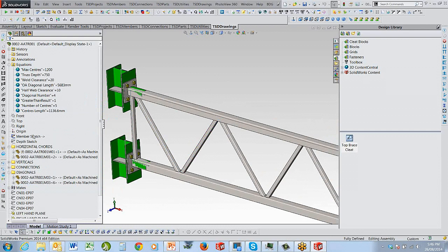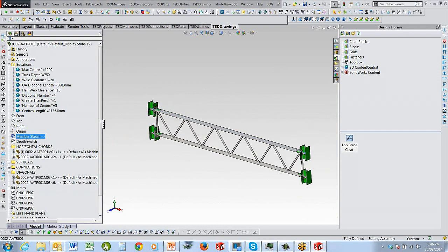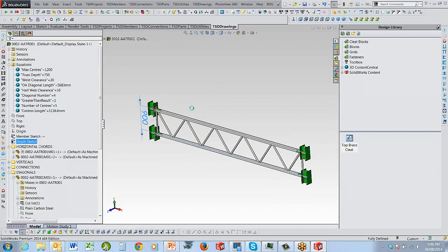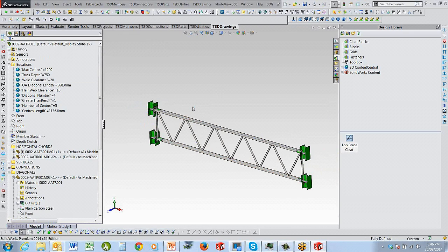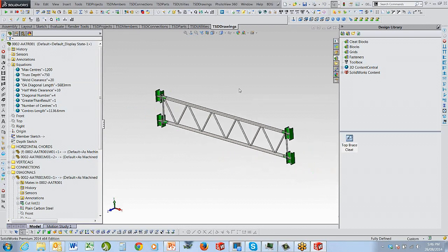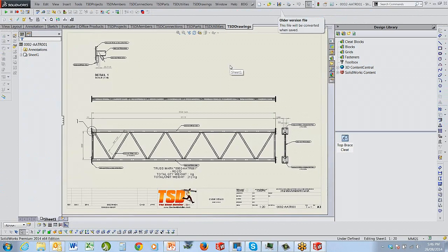So you can see how everything hangs off that one member sketch, and that one member sketch drives the entire truss. I can obviously change the height of it if I need to by going in and just doing a rebuild on that. That's pretty handy, pretty quick. And also with that truss, there's a drawing that's associated to it, which is already there, detailed.